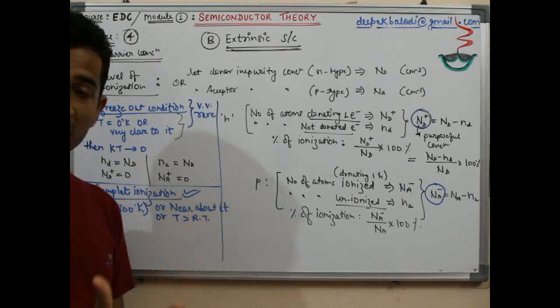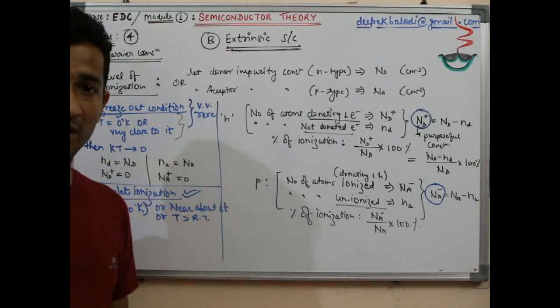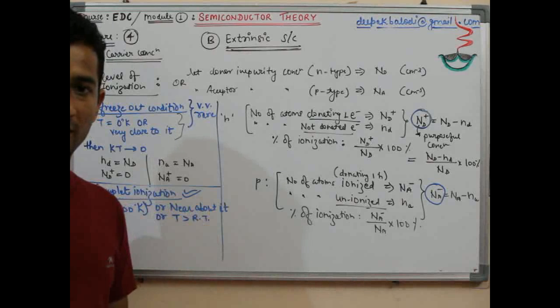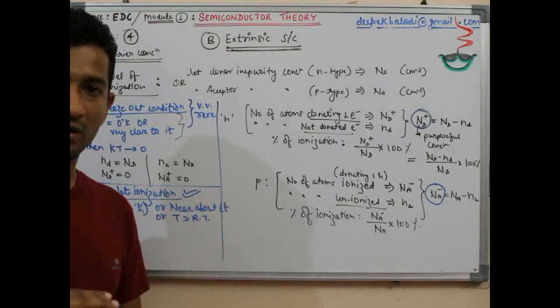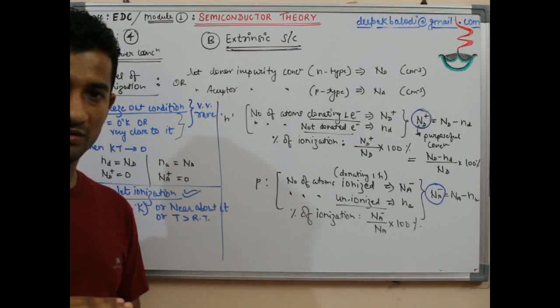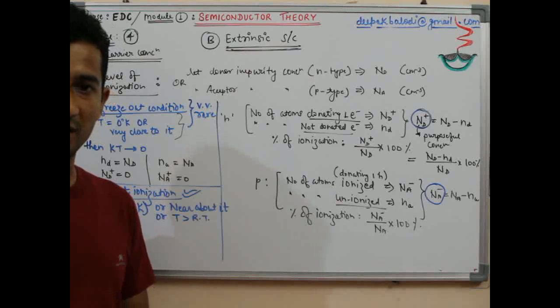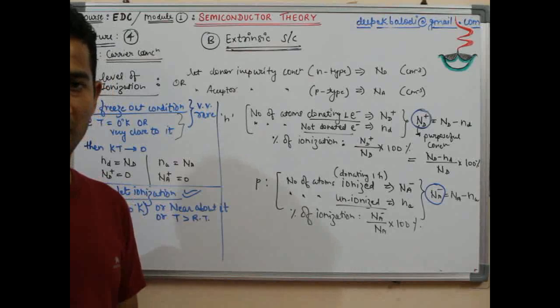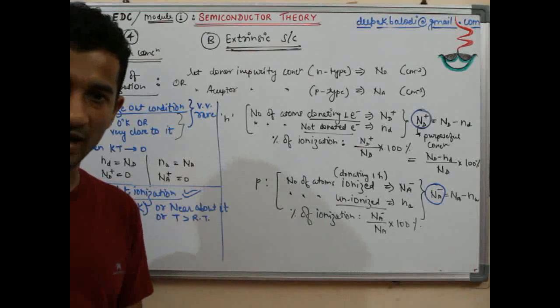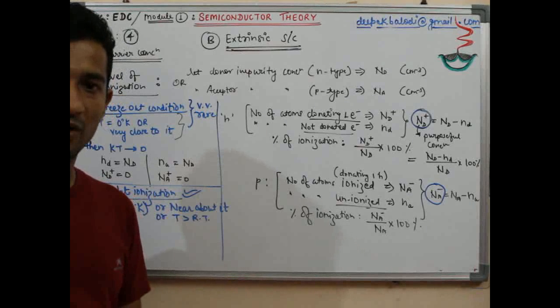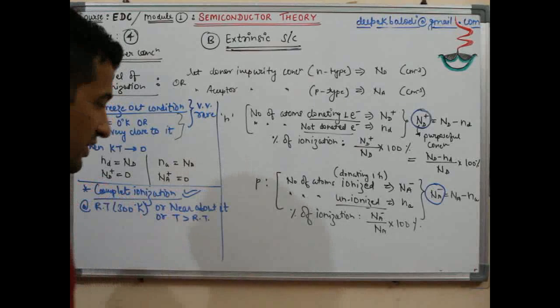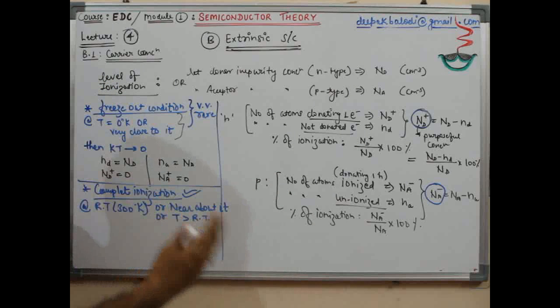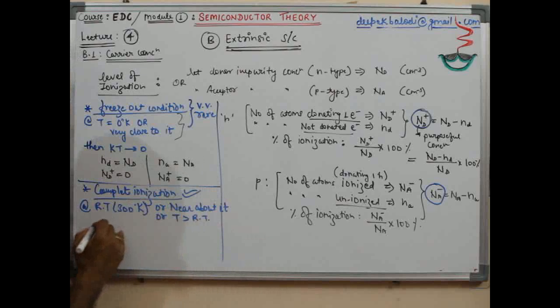So higher temperature is beneficial, because at high thermal energy it makes a better probability that the electron which is in the outermost shell of the impurity is definitely knocked out, or the hole is definitely knocked out. So the contribution definitely happens, and is confirmed by a higher probability when the temperature is higher. So then